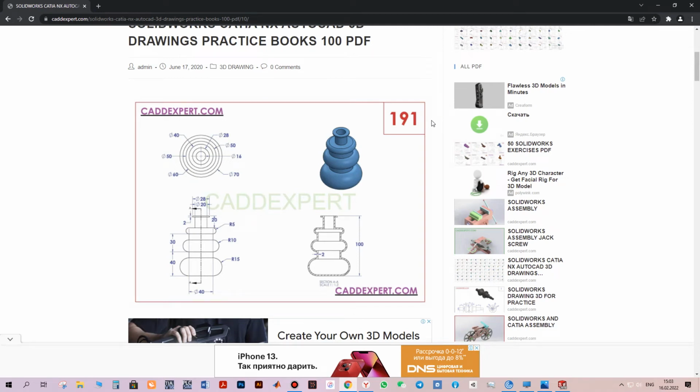Hello everyone, let's start our first SolidWorks example. Today we will model this object. So first of all we can think how can we model it. For example, here we have front view and we can probably just draw the right part and then we can rotate everything about the center line. So we draw this part, then rotate it, and we will obtain this object.